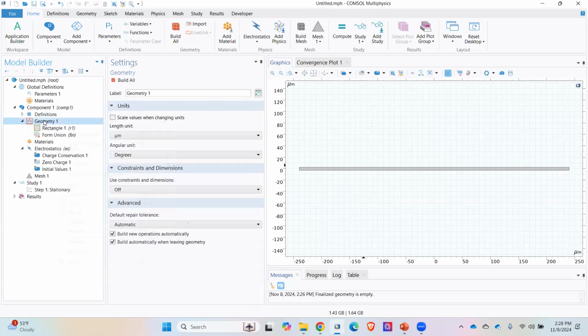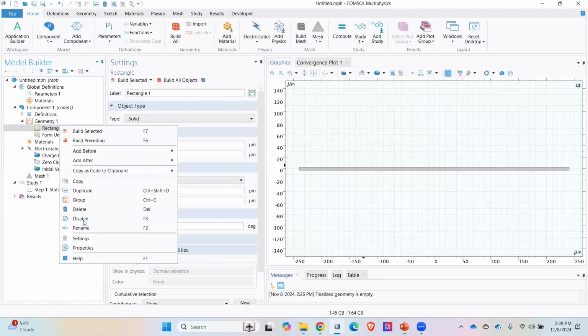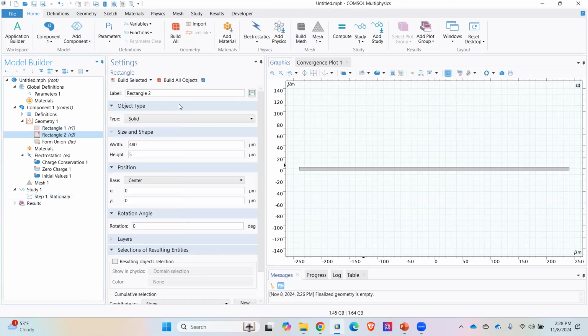Otherwise, you should go to the geometry and again make a rectangle. So if I just duplicate it, same thing will come. Now I want to change the location. I want this plate moving upwards, and the gap is 10. So I'll be moving this one upwards. So I'll just type -10, let's say. Sorry, plus 10. If I try plus 10, it moved up, right?